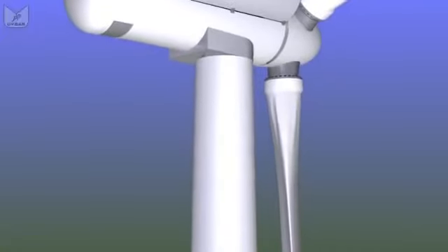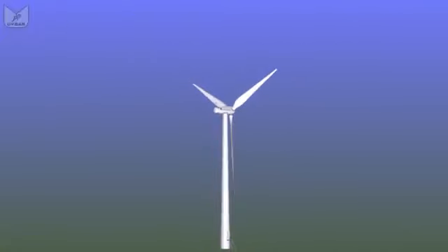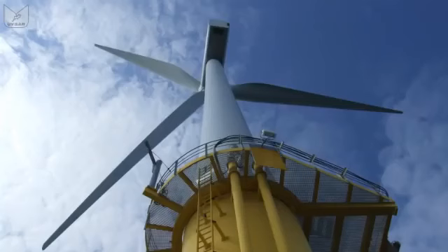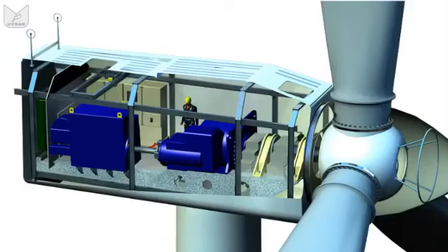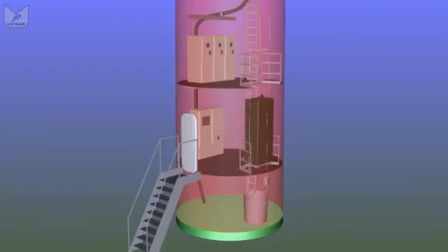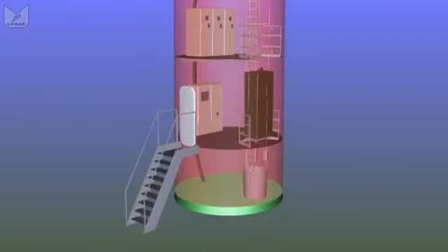Now, the layout of a larger turbine is broadly similar, but some of the components are in different places, so let's start by looking at the tower section of a typical 2 megawatt turbine. Where we place the high voltage transformers in multi-megawatt turbines is a lot more variable. Quite frankly, we have a lot more room, so we can decide if they can be in the nacelle, they can be at the base of the tower, they can be on platform 1 in the basement, they can be outside in a hut. In this example, the transformer's at the top, so when we go into our door, the one thing we'll not find is a transformer.